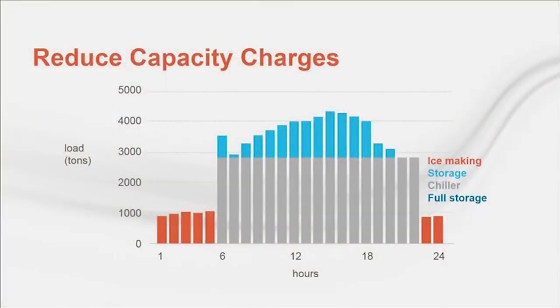The active approach can be just a small change compared to the more passive methods. Reducing loads during the times when capacity and/or demand charges are determined can be built into the system design, or they can be dynamically or operationally performed when these peaks are likely to occur. Let's take that known issue of 3 to 6 p.m. in the summer. For example, if you have a thermal storage system, you're already reducing your cooling load using it on the summer days between 3 and 6 p.m.